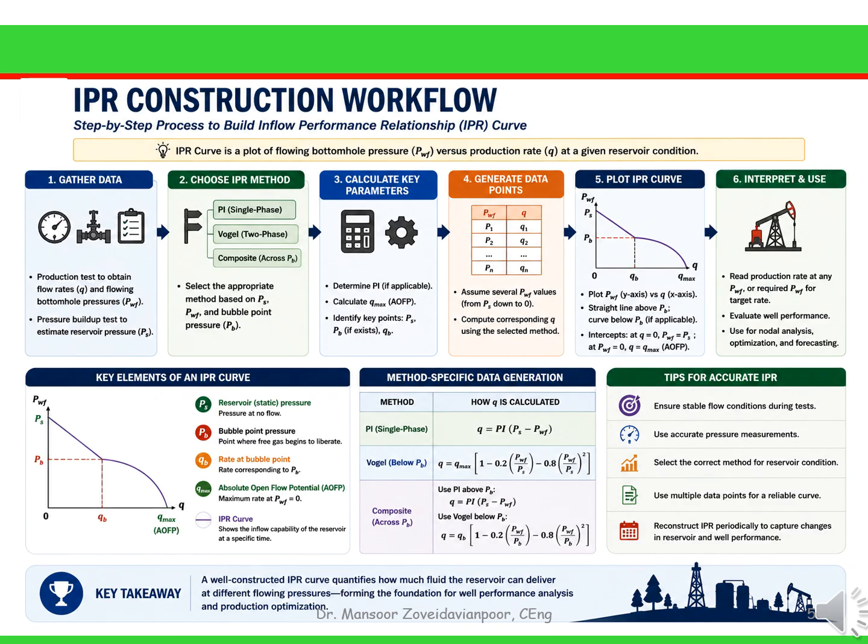Now comes the engineering insight. What happens if we lower the bottom hole pressure? Production increases. What if the reservoir pressure declines over time? The entire IPR curve shifts downward, and the well delivers less fluid.